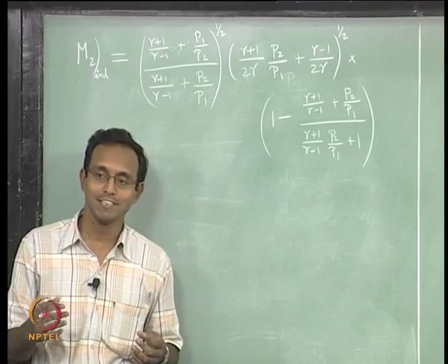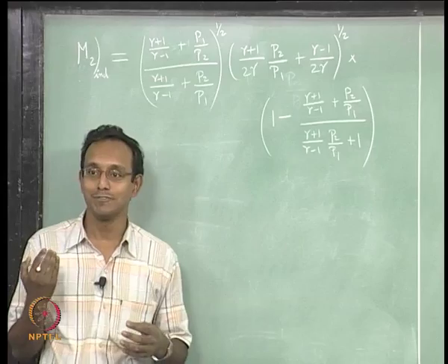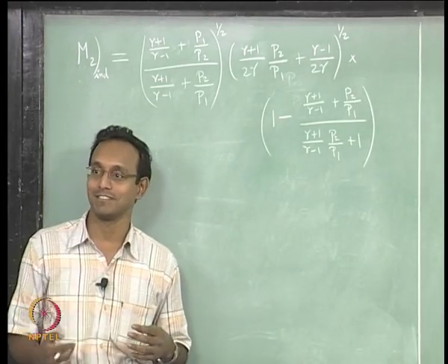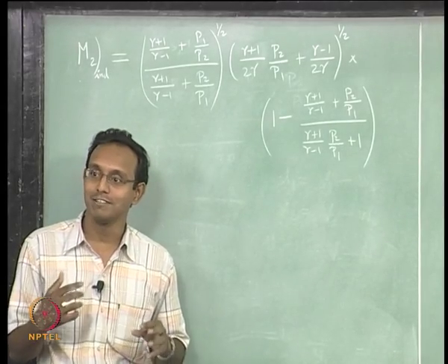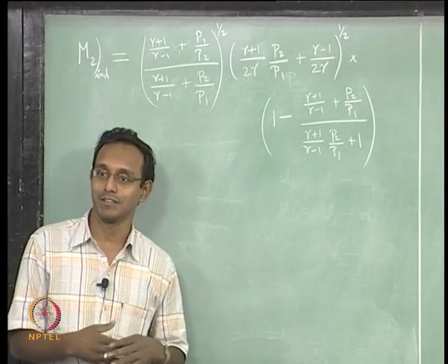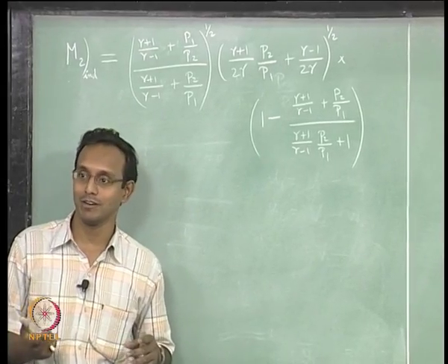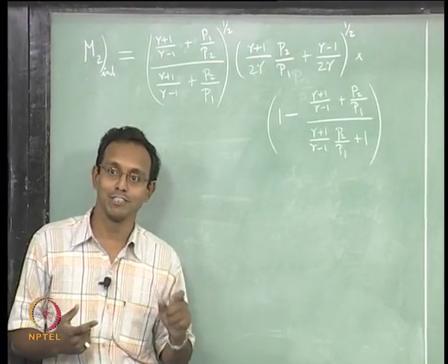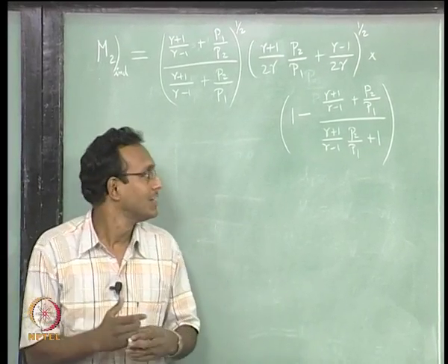Okay. If that is the case, there was a point where it should have crossed from subsonic to supersonic. There must be some P2 by P1 at which it will cross from subsonic to supersonic. That is, if I want to create a supersonic flow behind my shock, my compression ratio for that shock should at least be some value. How will I find that?